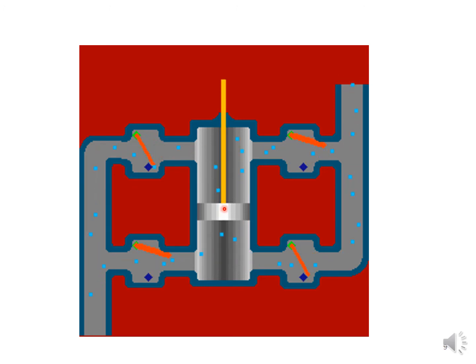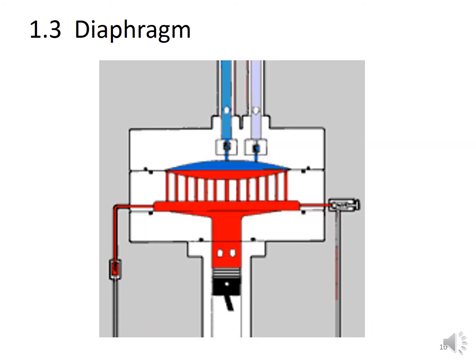So now the same piston is delivering more quantity of air. The capacity increases. Instead of two single acting compressors, you can use one double acting compressor. See, quantity. Okay, that's enough. Let's go to other one now.